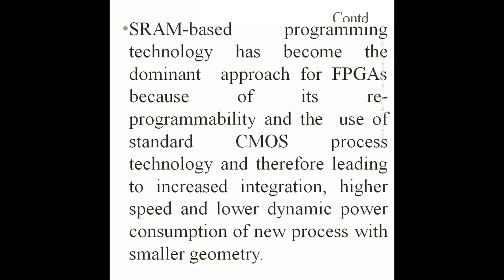SRAM based programming technology has become the dominant approach for the FPGA because of its reprogrammability and the use of a standard CMOS process technology, leading to increased integration, high speed and low dynamic power consumption of a new process with smaller geometry. Overall, in static RAM based technology, the memory elements are purely based on the SRAM CMOS process. It is called reprogrammability: whatever data is stored in memory, we can read as well as write.